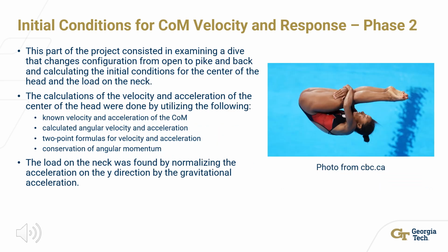So phase 2 instead consisted in examining a dive that changed configuration from open to pike to open again, and calculating the initial conditions for the center of head and the load on the neck. The calculations of the velocity and acceleration of the center of head were done by utilizing the following concepts. In particular, the known velocity and acceleration of the center of mass, the calculated angular velocity and acceleration, the 2-point formulas for both velocity and acceleration, and the conservation of angular momentum.